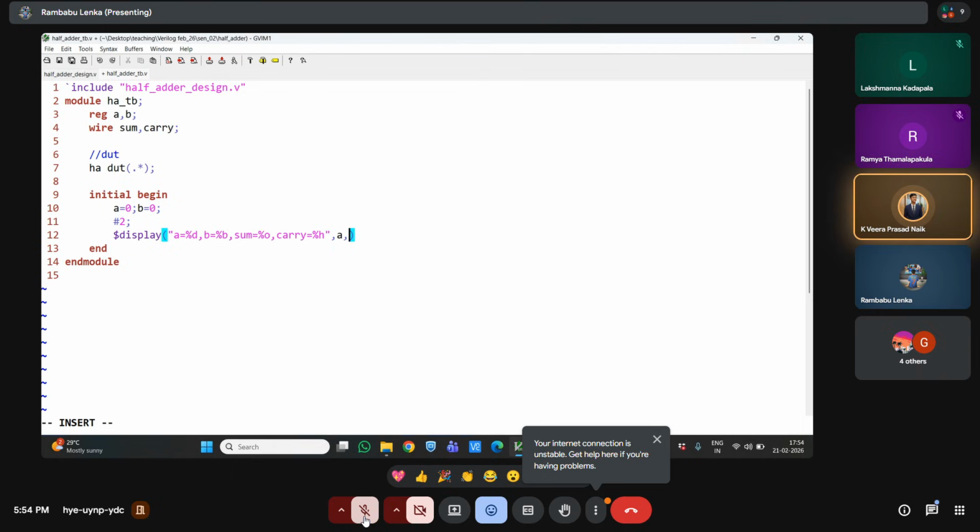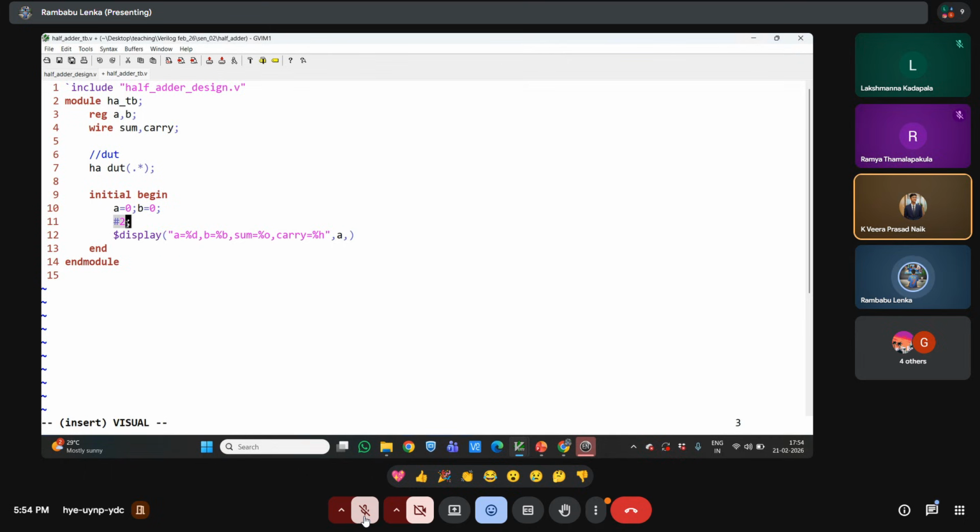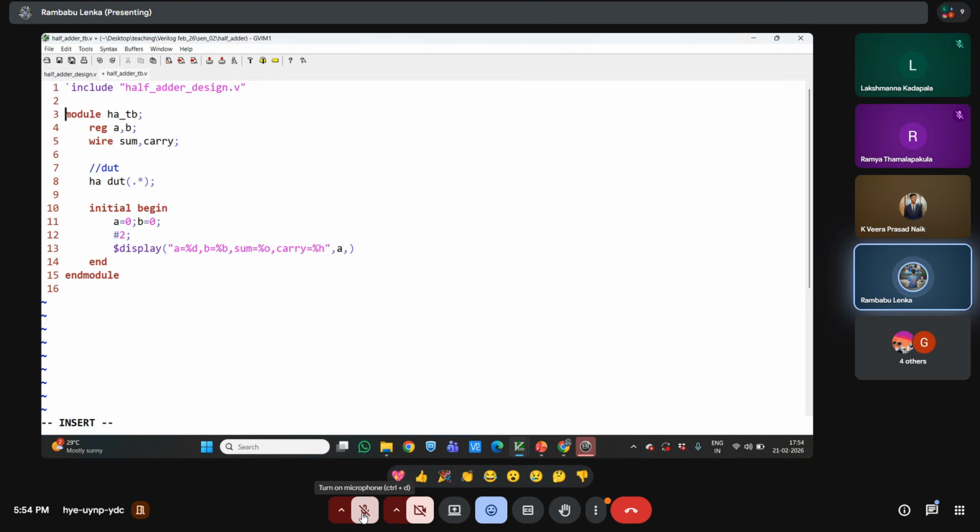Sir, why did you write hash 2 there? Yeah, why am I giving it? This is a time delay. Sir, you didn't mention nano or picoseconds. Why, can you understand? If it is not there, I have to mention the timescale tick timescale. Pico or nano, if you give either it is fine, or else the tool has some default time.